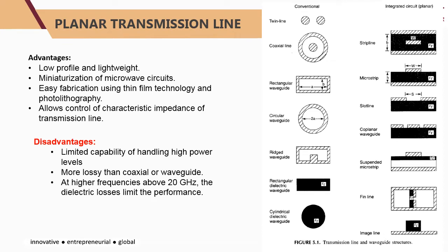Compared to the conventional waveguides that I have shown earlier, such as the coaxial line, rectangular and circular waveguide, today we look at the planar transmission line that is usually used in integrated circuits or planar structures. Usually the structure can be printed directly on the substrate.